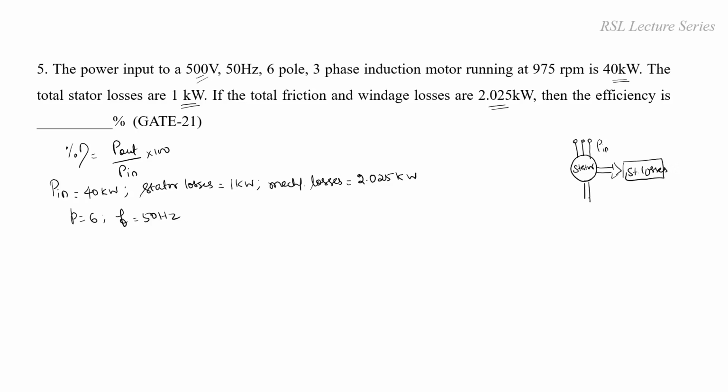The output of the stator is the power P2. This is given as input to the rotor. So P2 is the output power of the stator or the input power of the rotor. This P2 has to supply the rotor losses. Rotor losses in general are rotor copper loss only, because the rotor core loss is negligible.